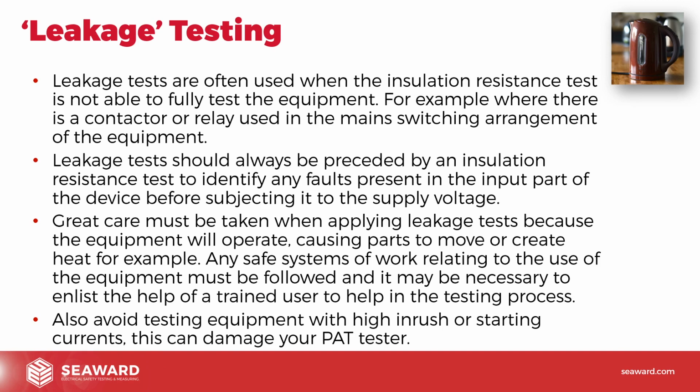So yeah, we might have grinding equipment. You might have a grinder, and you might not be trained in the safe use of that grinder. You might not be approved to actually remove the grinding discs. If we're carrying out a test on a grinder, common sense would say that we take the grinding discs out. If we're going to carry out a test on a saw, we take the saw blade out. So we're minimizing that risk. But again, we might not be trained to do that. We might not have the PPE. We might not have the certificate for doing it. So again, no problem. Get a trained user to help you to carry out that test, so we're making sure that we're adhering to the precautions.